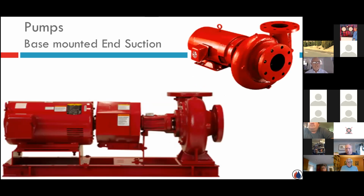As you move into the more commercial side with bigger loads, greater flow rates, et cetera, you get into what's referred to as base-mounted end suction pumps. End suction means that at the end of the pump, that's where the suction is. That's where the return water, maybe from the boiler, if you will, is entering into the impeller that's spinning in this casing here, and then it's going to be discharged out the top. So end suction, discharge out the top. Close coupled with the little foot right here, or again, a bigger, almost like you could say, a three-piece.